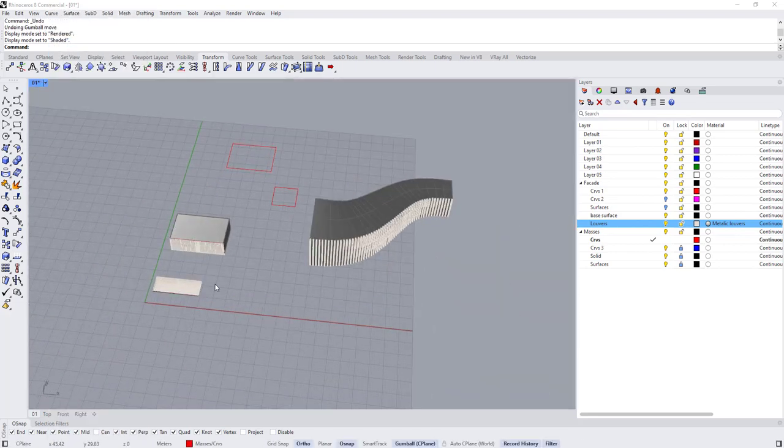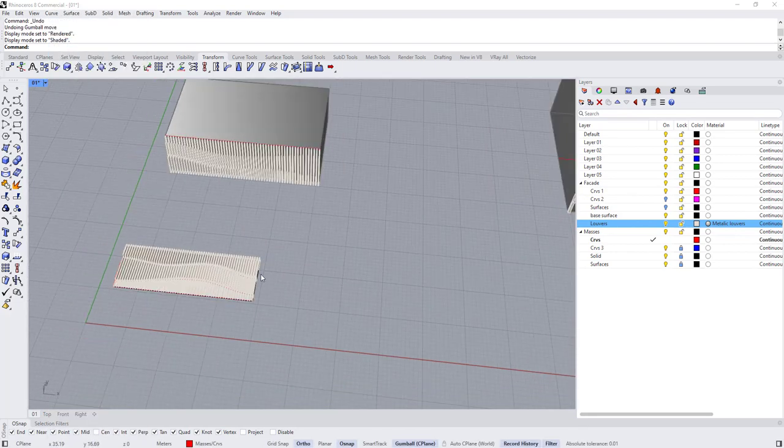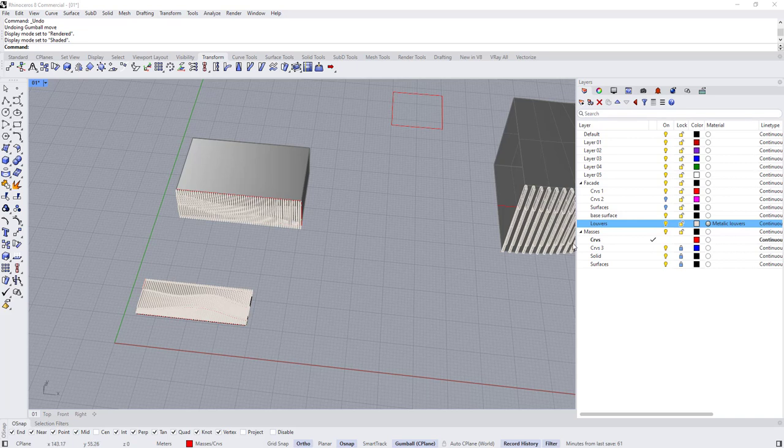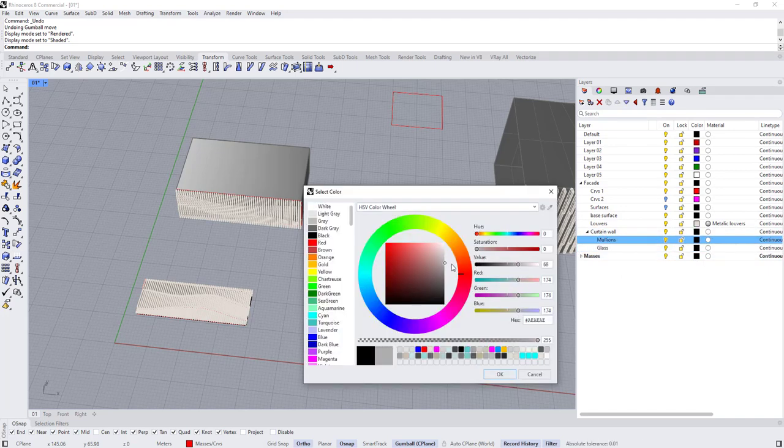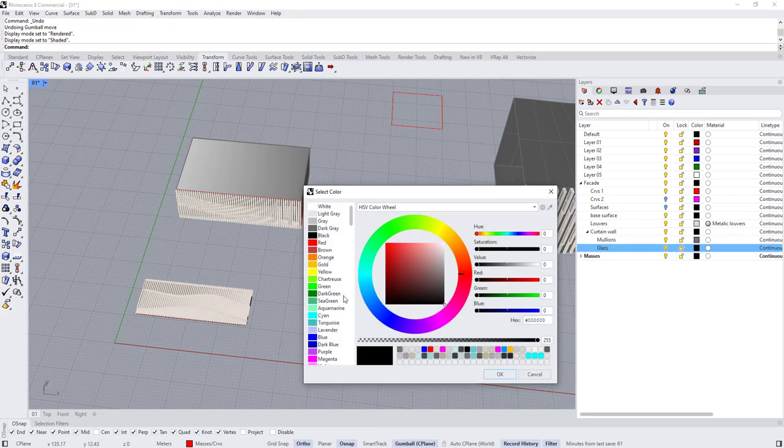Okay, now remains modeling the curtain wall. So the curtain wall, to model it on something like this, we are going to use the same method. So I'm going to create a new layer here on the facade. So come here and choose new layer. Name it curtain walls, and let's add a sublayer and another sublayer. The first one is going to be mullions, so type mullions, and the second one, let's name it glass. Let's give this some kind of dark gray color, and this one